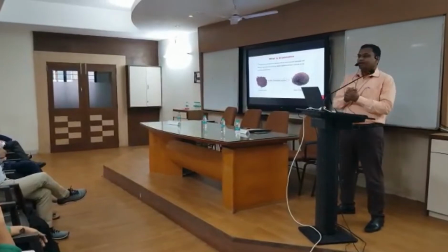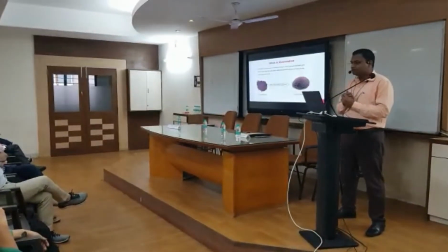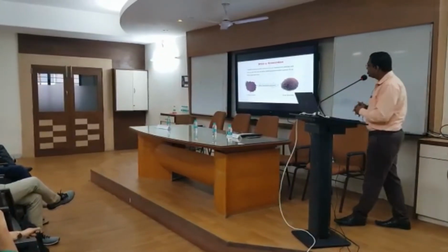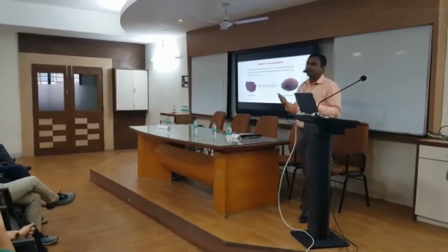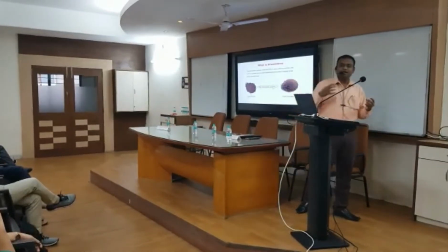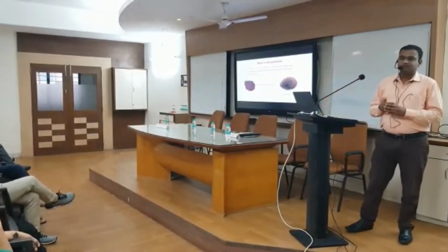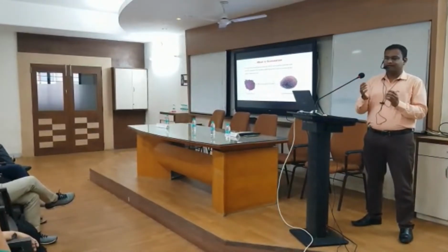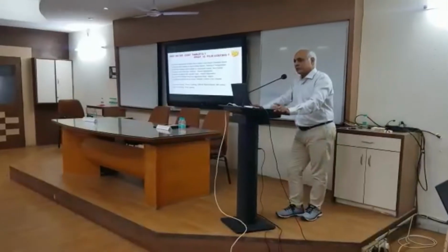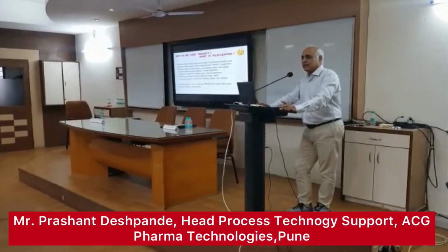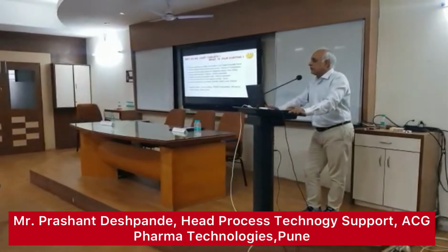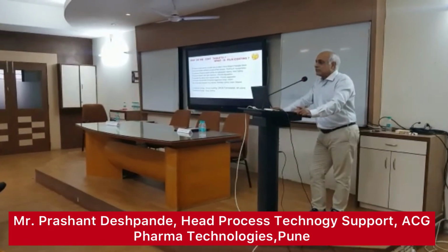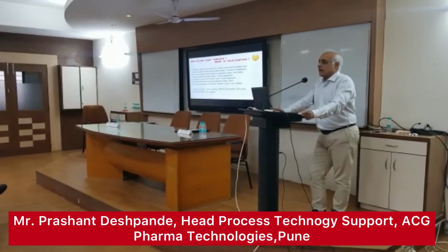So why is granulation required and what is granulation? Granulation is a process wherein one or more powder particles are combined together with the help of a certain binder to form granules, and those granules will have certain flow. It also helps during strip packing, during container packing, and also during dispensing. It also helps in improving the surface if we have a subsequent coat.